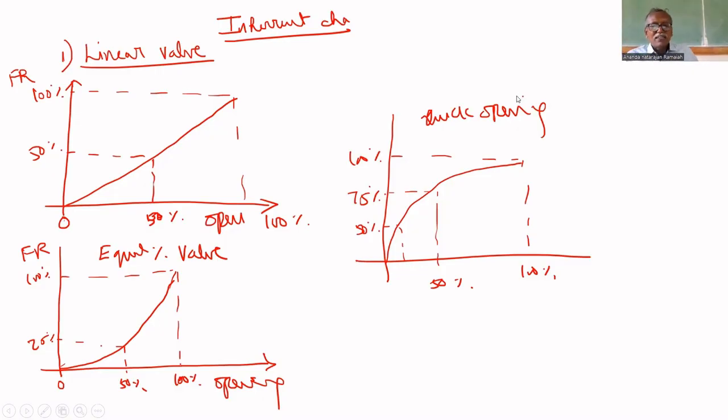You can understand from where we are giving the air inlet whether it is air to open or air to close. If it is at the bottom, air to open. If it is at the top, air to close. That's all.